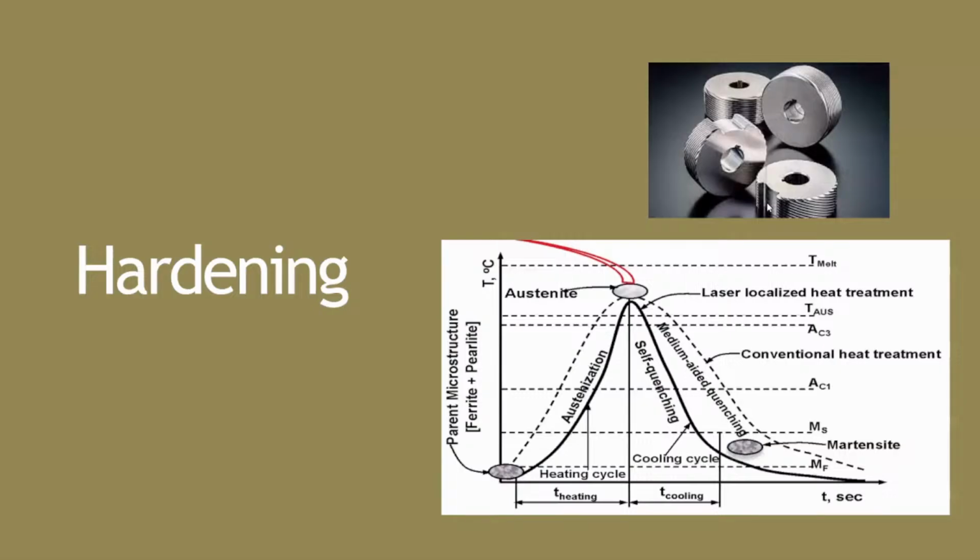Okay, so there are useful variations. Case hardening adds carbon or nitrogen at the surface first. So you end up with a wear resistant skin and a tough core, preferred for gears and shafts. Induction hardening skips chemistry changes and uses electromagnetic coils to heat just the surface quickly, then quench it, giving you a hardened outer layer with minimal distortion.